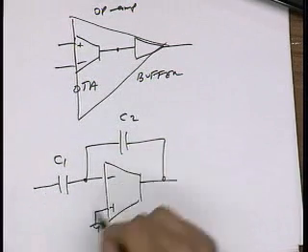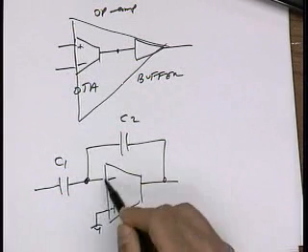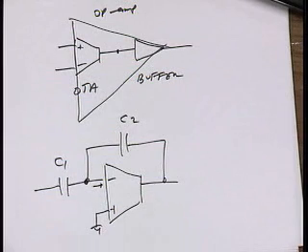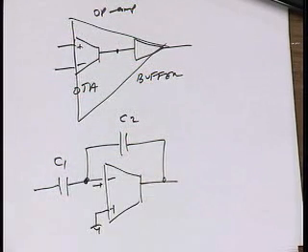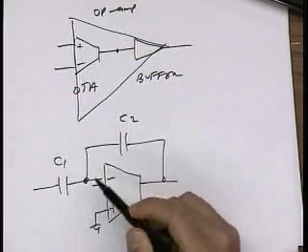That's right. First of all, this circuit doesn't work at DC, right? And the other issue is that this node is a high impedance input, and so there's no current going into this node. So what's the voltage at this node? It's kind of unknown. It's determined by leakage in the circuit. So the voltage at this node, because there's no DC feedback, is pretty much an unknown.